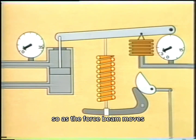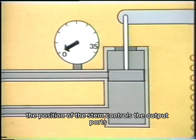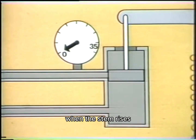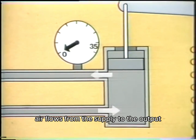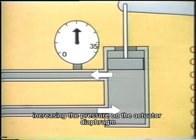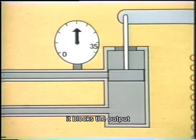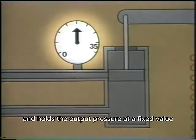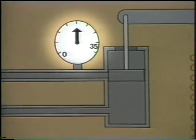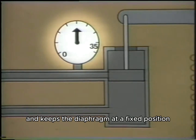So as the force beam moves, the stem of the pilot valve moves with it. The position of the stem controls the output port's airway. When the stem rises, air flows from the supply to the output. Output pressure increases, increasing the pressure on the actuator diaphragm. When the stem is partially lowered, it blocks the output and holds the output pressure at a fixed value. This pressure is trapped in the actuator and keeps the diaphragm at a fixed position.